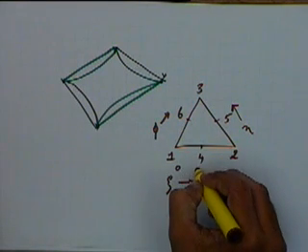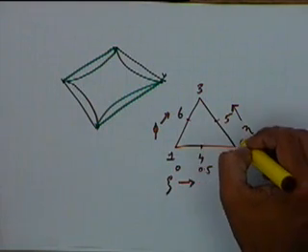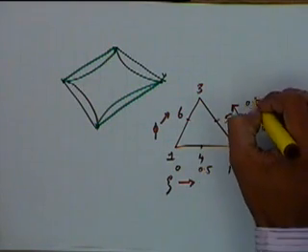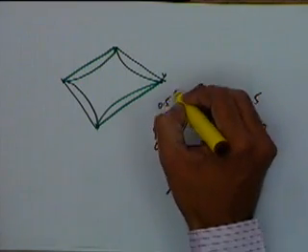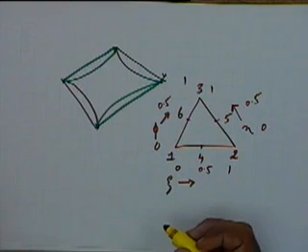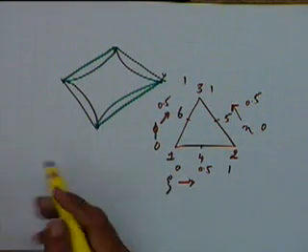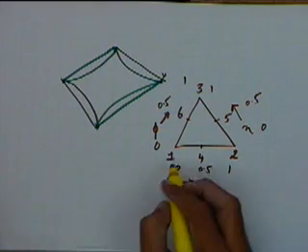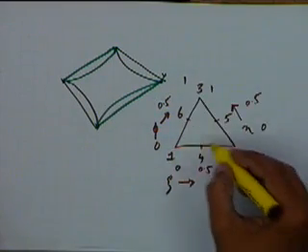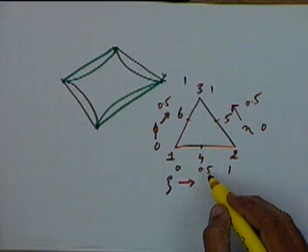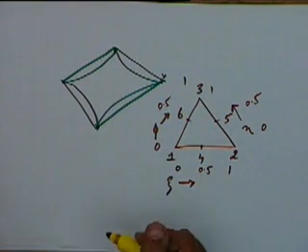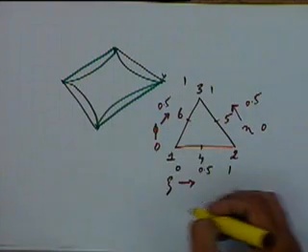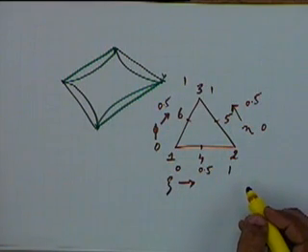Okay, let us say this is 0, maybe 0.5 and 1, again eta is 0, maybe 0.5 and 1, and again phi is changing as 0, 0.5 and 1. And again the 6 shape functions can be defined in a similar manner. For node 1 I will consider this straight line and this straight line. For node 2 I will consider this straight line and this straight line, and so on. So this way we can define a 6 noded triangular element also.